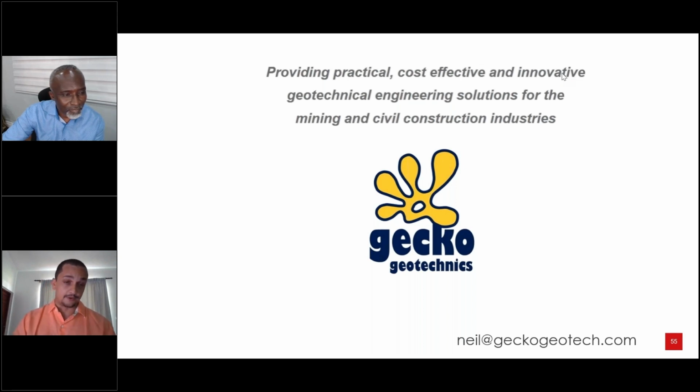Actually, sorry, back to the river one, ground-based radar, prisms, all of the traditional tools can also do it. For subsidence from mine workings or other underground excavations, if displacements are visible at the surface, InSAR will detect them. It's quite accurate. Otherwise, there are other methods. If you know of an excavation, deep hole extensometers in boreholes and other things like that can look at the potential for caving. Thanks, Neil.